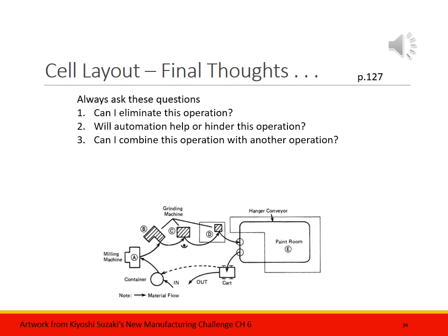Because if they're both running in the mill, it's a piece of equipment I don't need. But secondly, maybe I can interpolate that circle. I don't have to run it in a lathe. I'm not going to block it up and lock it into a spindle and spin the darn thing. There's enough math and enough precision, and the tolerancing is such that if I interpolate that diameter, I am good enough. Let's get rid of the lathe. One mill operation. Yeah, it might cost me some cycle time, but the door-to-door cycle in the cell just got improved. All right, enough said there.